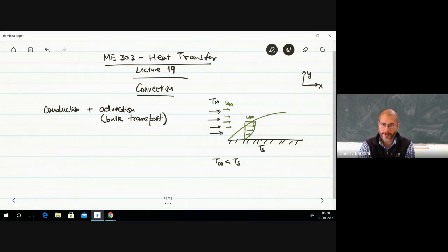That increases the rate of heat flow from your body, which results in the cool feeling. The rate of heat transfer from your body to the ambient increases as you switch on the fan. That basically means that you increase the heat transfer coefficient because of convection by increasing the flow rate.